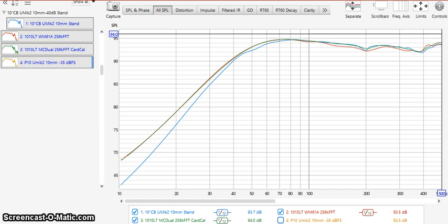The method to measure is generally to put it within a 1/4 inch. In this case, I put it 10 millimeters. It's not a fixed distance. There is one that you can find if you do some research on that, but in this case, for a 10-inch woofer that I'm measuring, the 10 millimeters works out pretty closely to the recommended, which is where I had all three microphones, at least initially, when I did the single microphones. The mode compensator is a dual mic system, so it uses two mics at a further distance. However, the match was nearly perfect with the Panasonic close mic measurement.